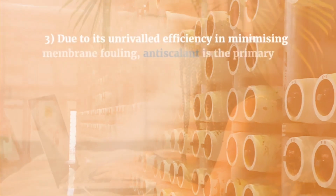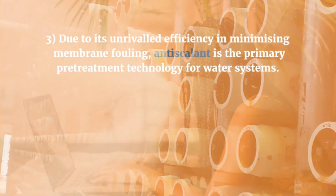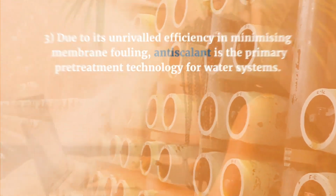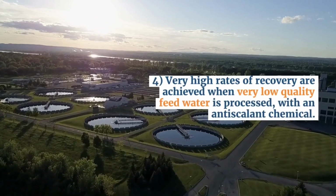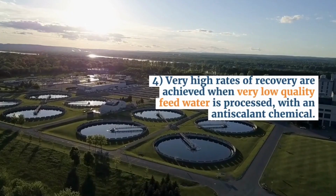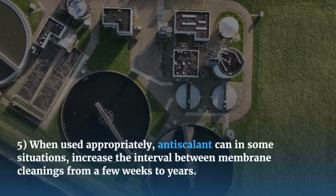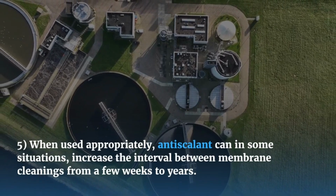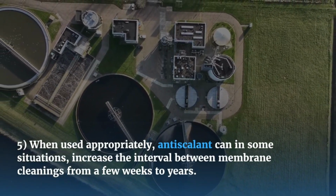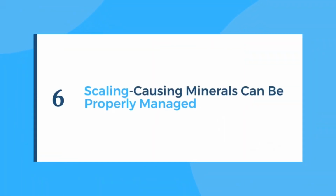3. Due to its unrivaled efficiency in minimizing membrane fouling, antiscalant is the primary pretreatment technology for water systems. 4. Very high rates of recovery are achieved when very low-quality feed water is processed with an antiscalant chemical. 5. When used appropriately, antiscalant can in some situations increase the interval between membrane cleanings from a few weeks to years. 6. Scaling-causing minerals can be properly managed.